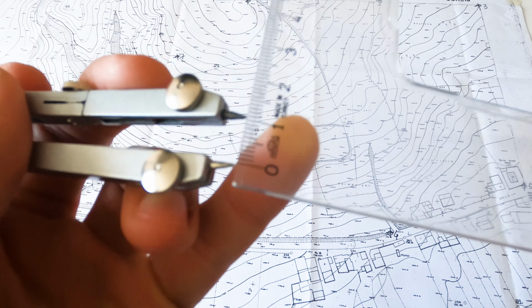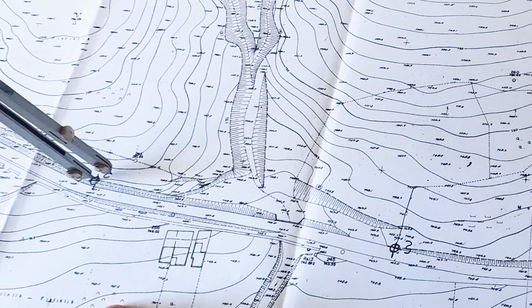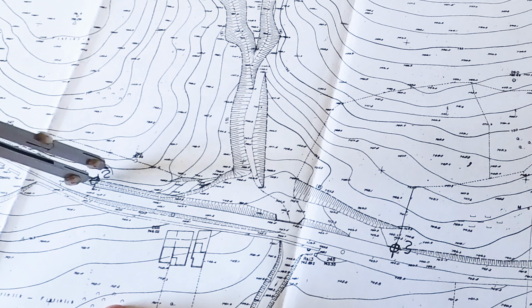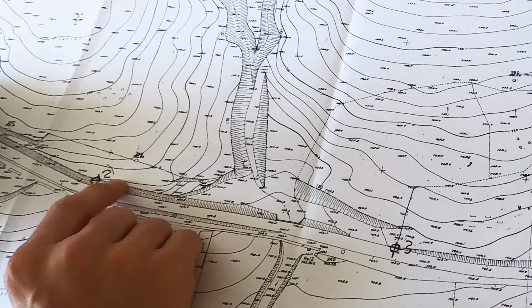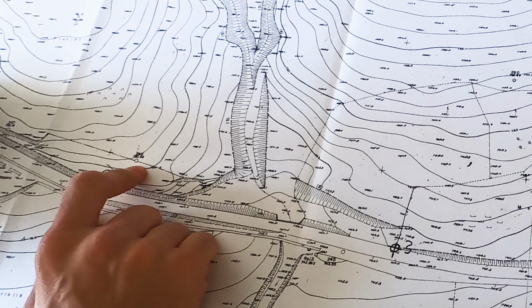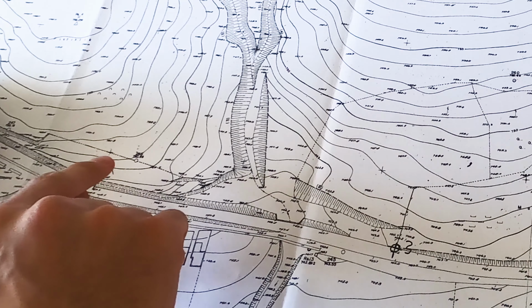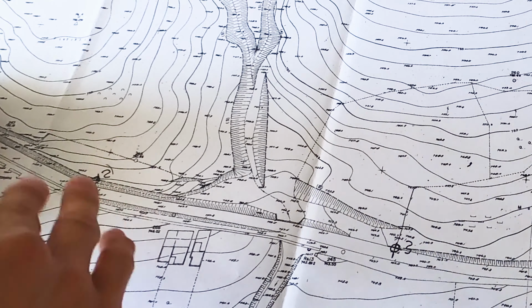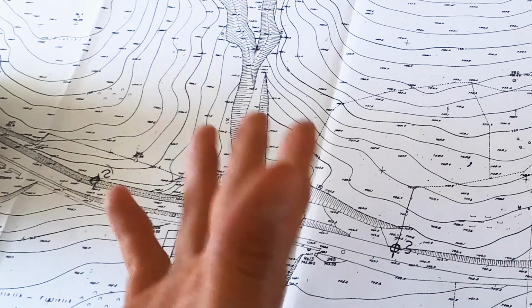And we start with our point in here. Starting from this point, we have to take the cut of the line on the other contour line, because from this contour line to this contour line, there is 1 meter difference in height on the site. And to achieve it, we need a distance of 11.11 meters on the site. That means 1.1 centimeters here.